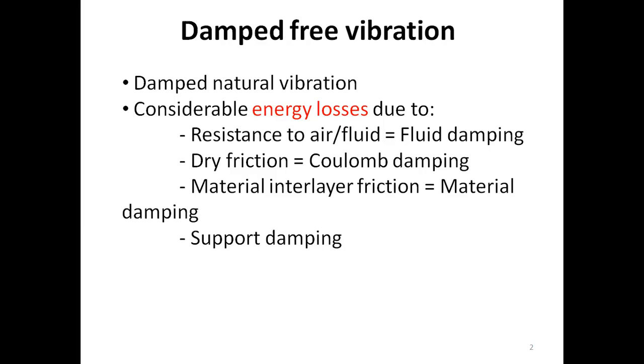So actually we are doing that in all those vibratory systems where beforehand we know that the damping in the system is less, it is ignorable, and by doing so it would have very little effect on the accuracy of the modeling and the accuracy of the answer of the computation.